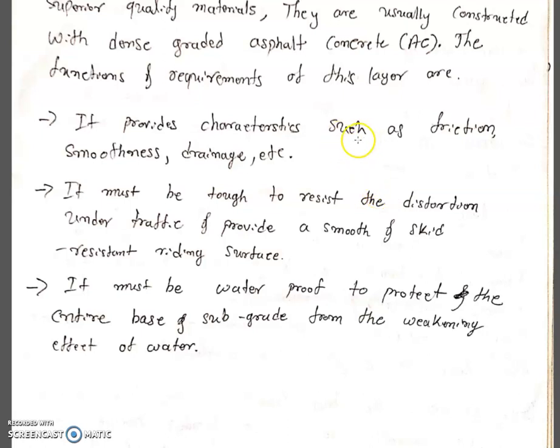It should not happen. It must be waterproof to protect the entire base and subgrade from the weakening effect of water. If water enters, if you don't provide the proper camber, if the water enters the base courses, then the pavement will fail.